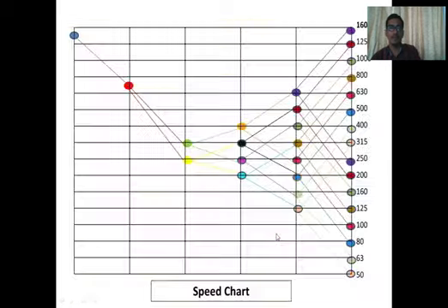Whenever we combine the ray diagram and the structural diagram, it gives us the speed diagram. So we put the different spindle speeds on the output shaft. From the lower side, minimum spindle speed, second, third, fourth, fifth, sixth, seventh, eighth, 9, 10, 11, 12, 13, 14, 15 and 16. So the total number of speeds achieved is 16. From the minimum spindle speed to the maximum spindle speed, we get the different spindle speeds using speed steps in geometric progression. So this diagram is called a speed chart.